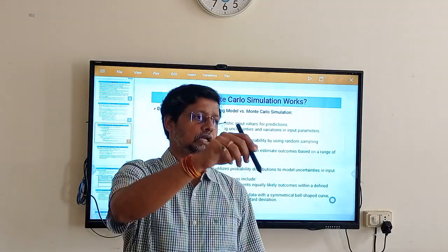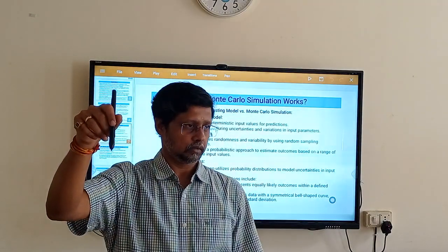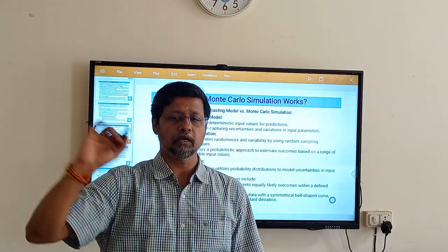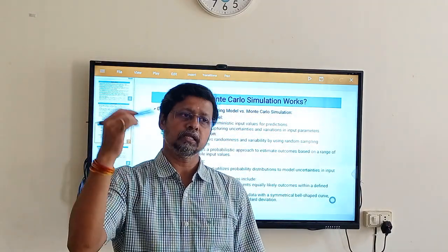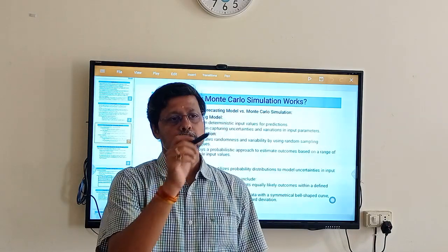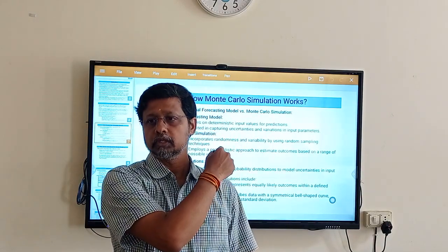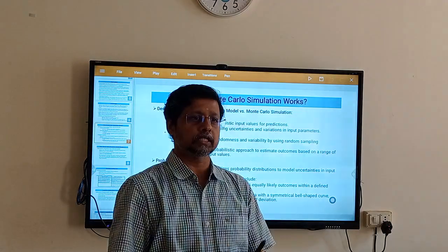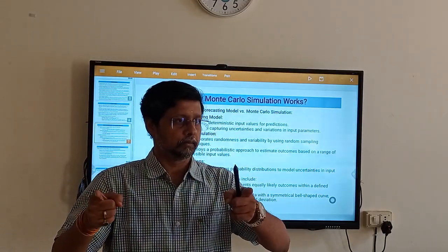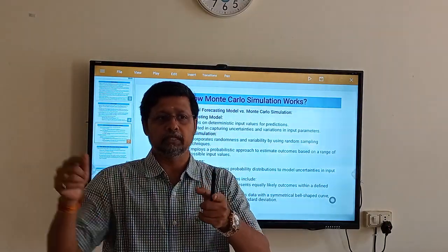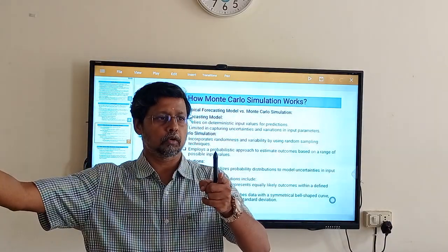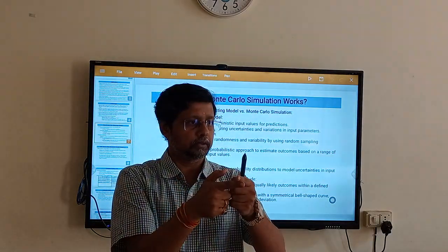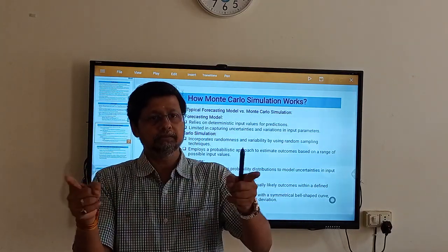So for a particular application, you will fix that value. Let's say 2 fm is not enough, I will go for 3 fm or 5 times the modulating frequency. But then again, that 5 is also finite. So in these cases, Monte Carlo simulation will test the entire range of samples. If the input range is 10 to 20 times the maximum modulated frequency, it will start from 10, end at 20, and then try to optimize.